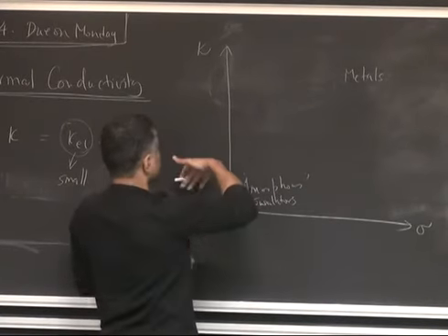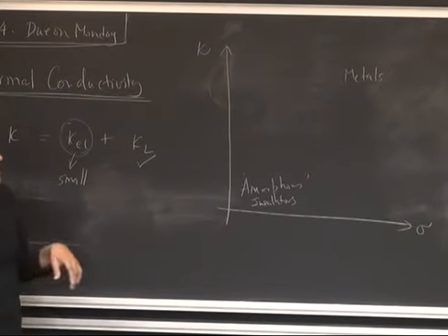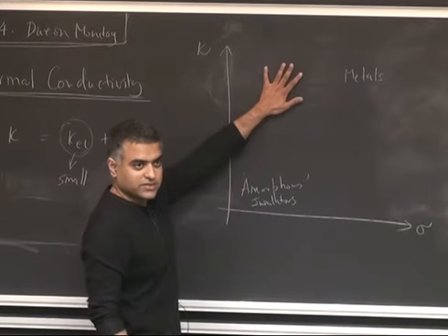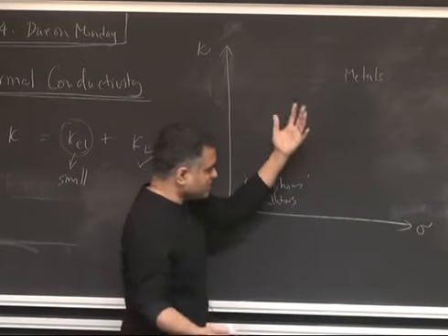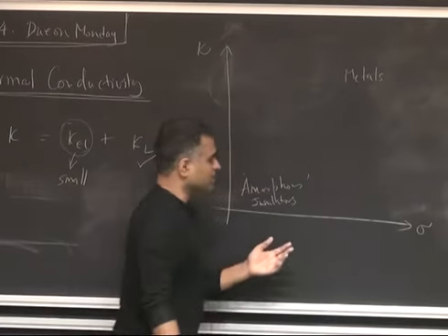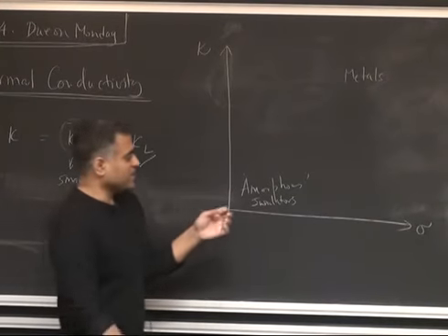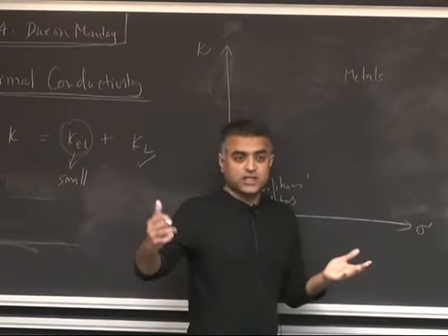What about this end? Low thermal conductivity but very high electrical conductivity. Any sort of materials that you know? Right. So this is kind of interesting. This and this are somewhat non-intuitive, and that's why we are going to focus on those. Both of them have to do with essentially compound semiconductors, or semiconductors in some sense. So here, if you think of a very narrow bandgap semiconductor, or even a semi-metal for that matter, the gap is 0 or negative. But then they must have very heavy elements in them. The atoms are very heavy, at the bottom of the periodic table, like bismuth telluride and things like that.